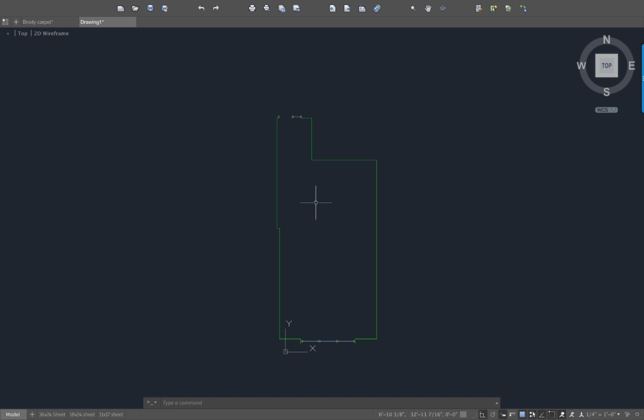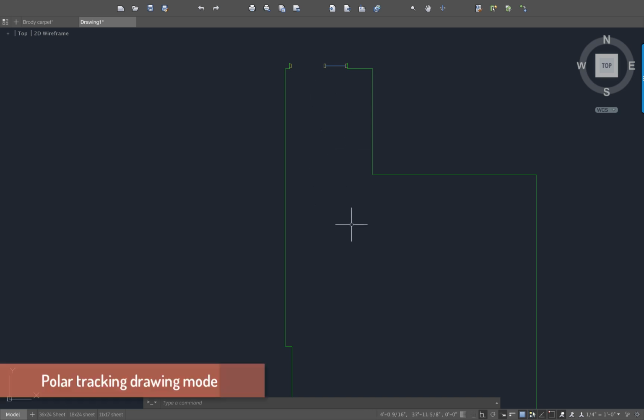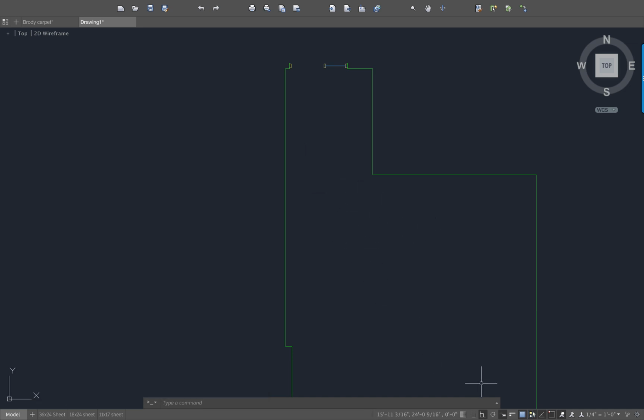And of course, I'm just drawing this example of a classroom. You'll want to take good field measurements, and I would recommend drawing an existing conditions type of drawing, which is very common, on the site. Take a laptop or something with you that you can draw all these measurements, because you're always going to miss something. And I know that those of you who could see that floor plan I was drafting from, there were definitely some missing dimensions. But the key thing is drawing using the ortho mode is absolutely important for that sort of thing.